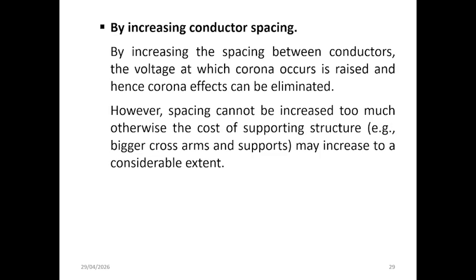Okay, this slide presents another important method for reducing corona effects by increasing the spacing between conductors. When the distance between conductors is increased, the electric field intensity around each conductor is reduced, which in turn raises the critical disruptive voltage at which corona begins. As a result, the likelihood of corona formation is minimized or even eliminated under normal operating conditions.